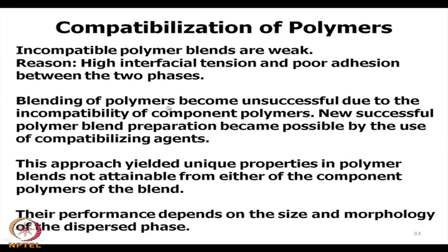Now, blending of polymers became unsuccessful due to the incompatibility of component polymers, but new successful polymer blend preparation became possible by the use of compatibilizing agents. This approach yielded unique properties in polymer blends not attainable from either of the component polymers of the blend.